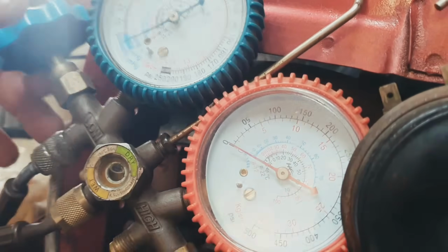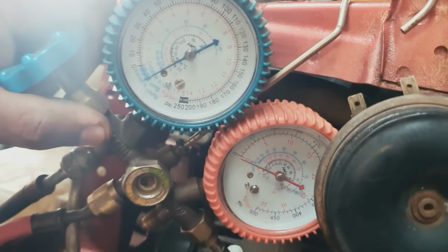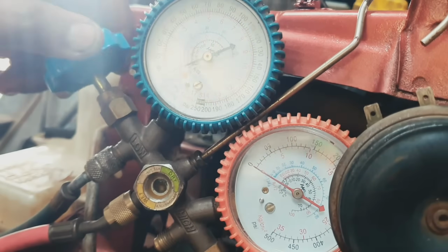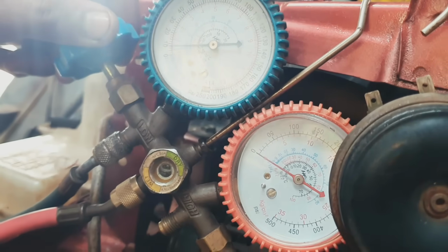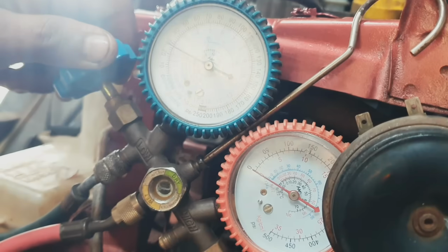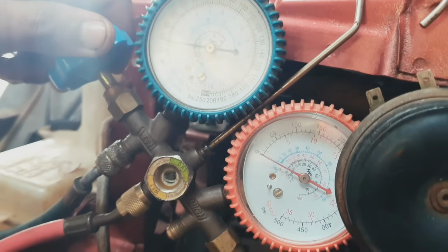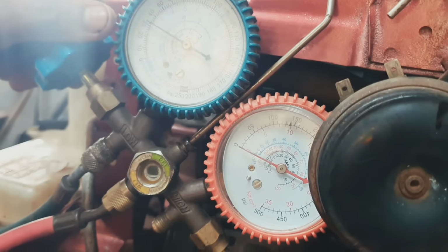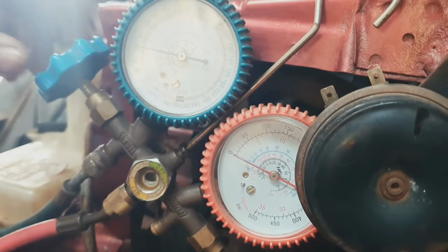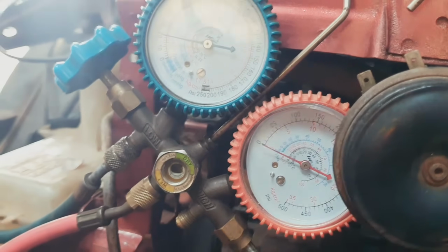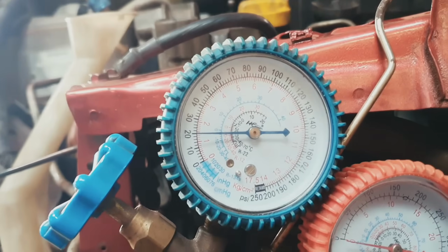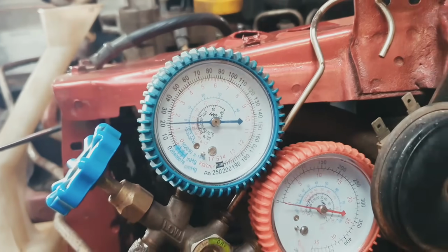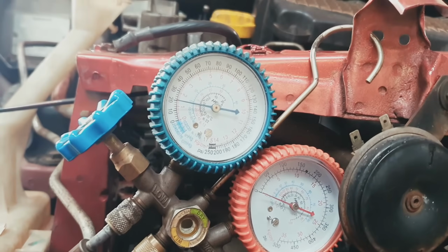Now you all can see it's holding a vacuum very well. Now I'm going to fill it with pressure and everything. We're going to fill up the right amount of AC gas, and once you're out of vacuum and you have refrigerant in your system, you will want someone to start the car. So now Nidan is going to start the car.